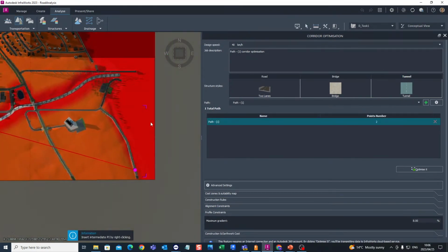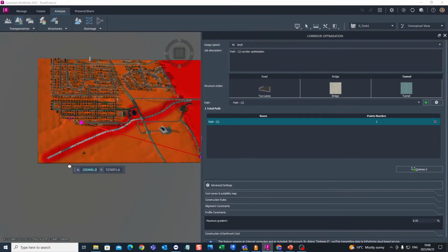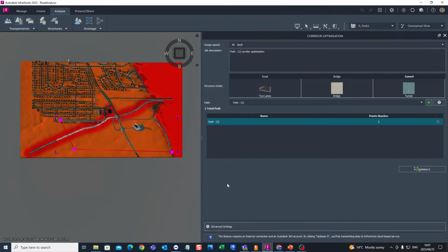That then places a sort of a box around everything. That's where you can see these markers there. They don't like to go outside the surface. Now that's a straight line. We might want to put an L-shaped curve in there, so we could right click and say add PVI. That will insert a PVI, and we can then maybe state that we'd like to go straight across the river like that, and you can add more if you wish. But that's pretty much the road that we'd like to travel, and we've got advanced settings that we can choose.